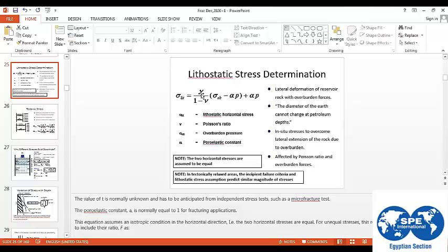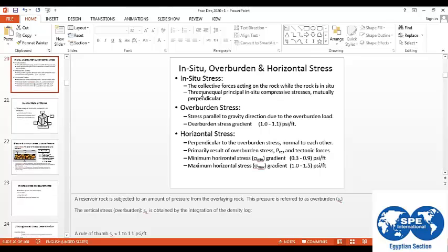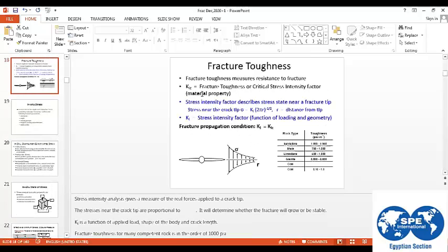You need higher net pressure to keep these fractures open. Also, the formation toughness, this term that we were discussing previously, will be different. According to what? According to the formation stress. This will control the propagation, and in this way will control the fracture half length. So if you have less half length, this means that you have higher height.